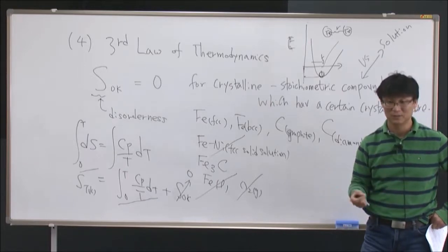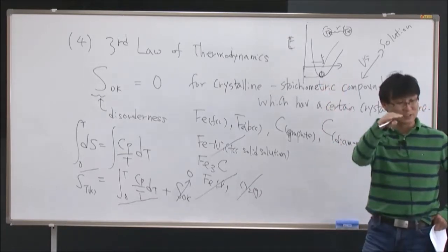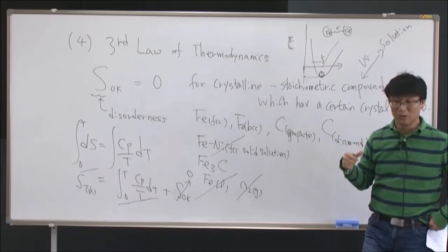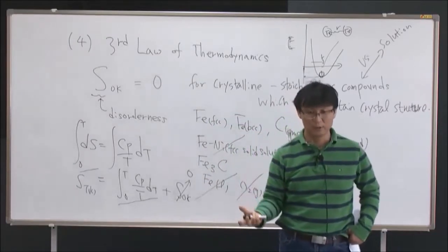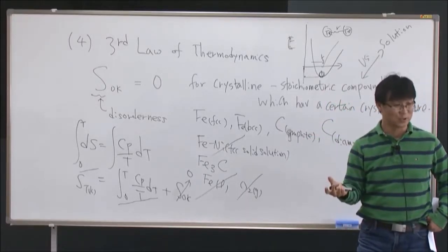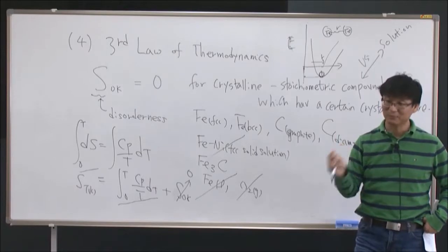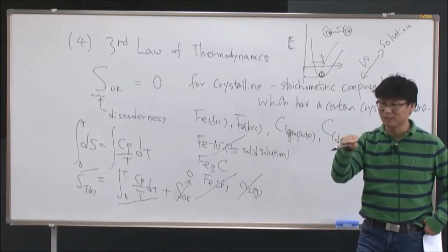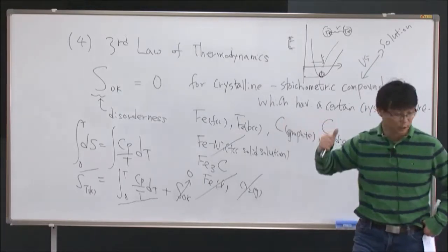So they have to make a certain assumption. That assumption is that instead of using this absolute value, we use a certain relative value for the enthalpy. We're going back to this point later. But what I really want to stress here is that because of the third law of thermodynamics, entropy has an absolute value. However, enthalpy doesn't have an absolute value. Enthalpy is a relative value all the time in thermodynamics. So, strictly speaking, Gibbs energy for the material is not an absolute value. It's a relative value based on certain assumptions, a certain reference state. We're going back to that one. Good? Third law of thermodynamics.